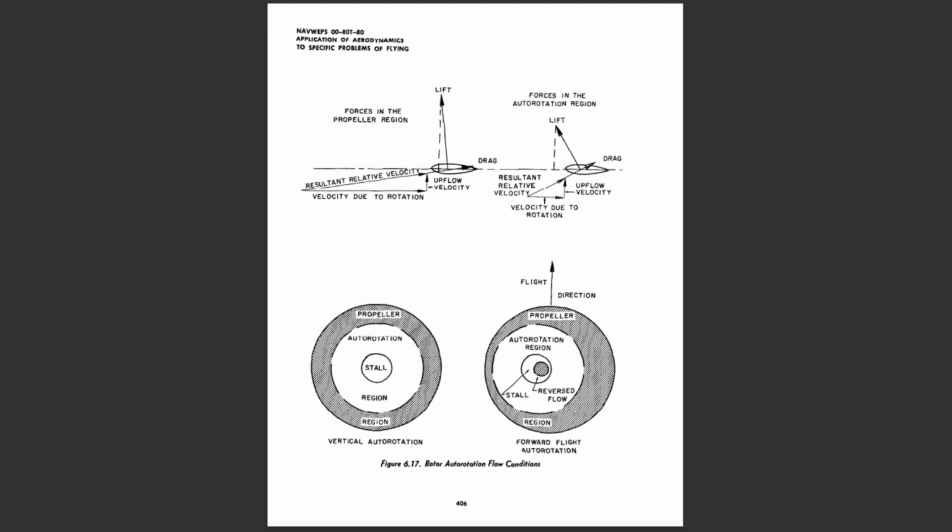In this case, the same forces are present, but the in-plane component of lift force is greater than the drag force, and this results in a net thrust or forward force in the plane of rotation which tends to drive the rotor. During a steady autorotation, there is a balance of torque from the forces along the blade, so that the RPM is maintained in equilibrium at some particular value.